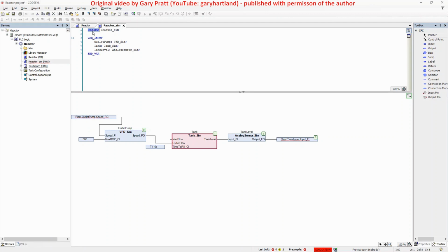In IEC 61131-3, a VAR_IN_OUT is a pointer under the covers. Then we need to change the hard-coded I/O to associate them with a pointer which will be passed to the simulator when it is called. If you don't completely understand this, it will make more sense in a few minutes. We will call the pointer myReactor and swap that into the I/O path names.